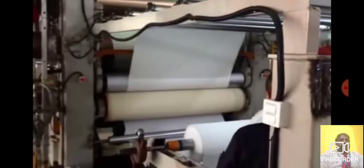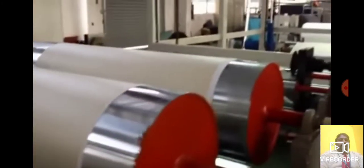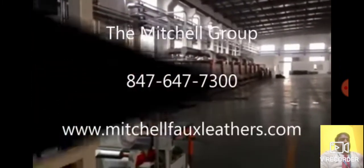So the third stage is then basically, as it got fused over there together, those were the two parts where they met. Here comes the clean sheet of PVC vinyl, and it gets cooled down through these cooling rollers and gets wound up through the backside here. And then after this, it'll go to this next station, which is the embossing station.